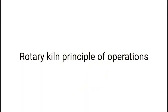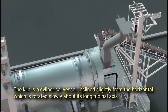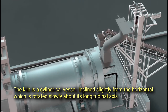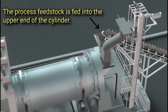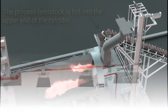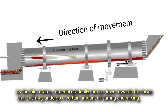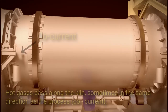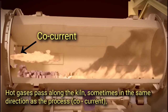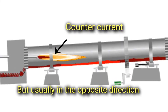Principle of operation. The kiln is a cylindrical vessel, inclined slightly from the horizontal, which is rotated slowly about its longitudinal axis. The process feedstock is fed into the upper end of the cylinder. As the kiln rotates, material gradually moves down towards the lower end, and may undergo a certain amount of stirring and mixing. Hot gases pass along the kiln, sometimes in the same direction as the process material, co-current, but usually in the opposite direction, counter-current.